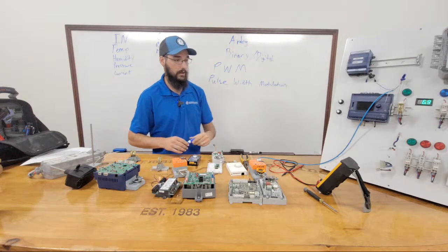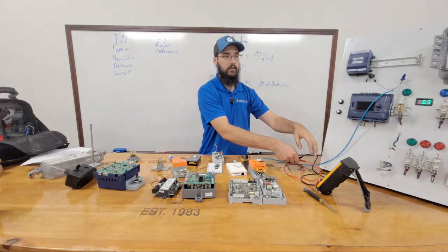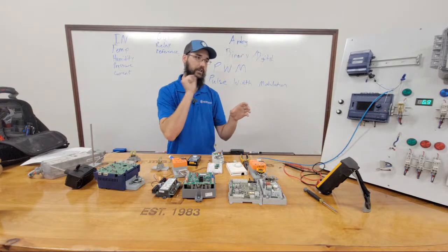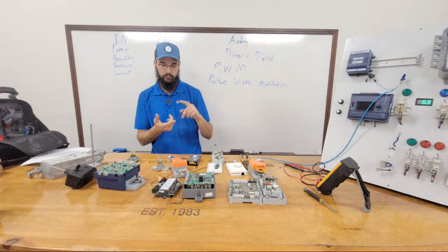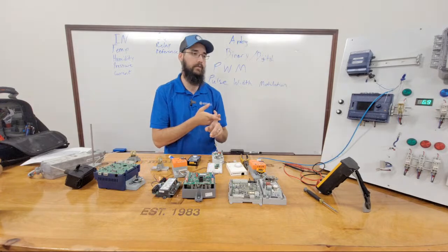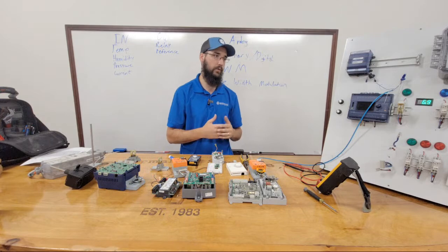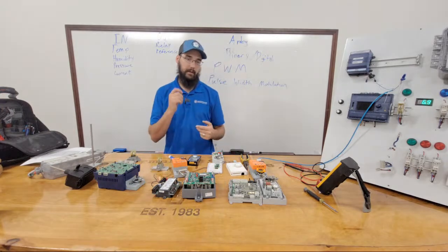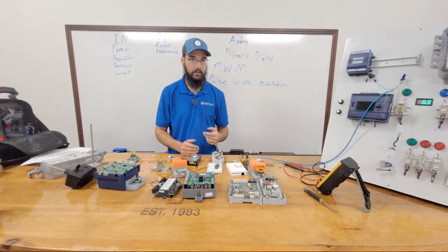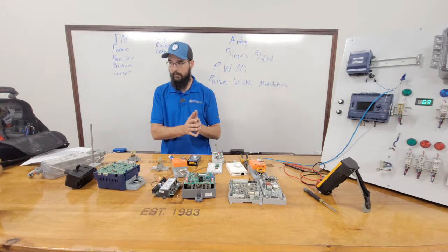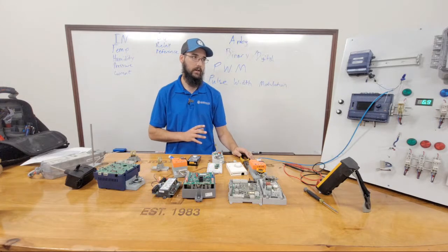And if you try to put your meter terminals on that and read, you're going to see that meter just flashing. Which is also why if you're ever reading the output of a VFD, and it says it's outputting 30 or 40 hertz, for example, and especially if you do not have a true RMS meter, your meter is going to freak out in its voltage, and it's going to be erratic and all over the place.